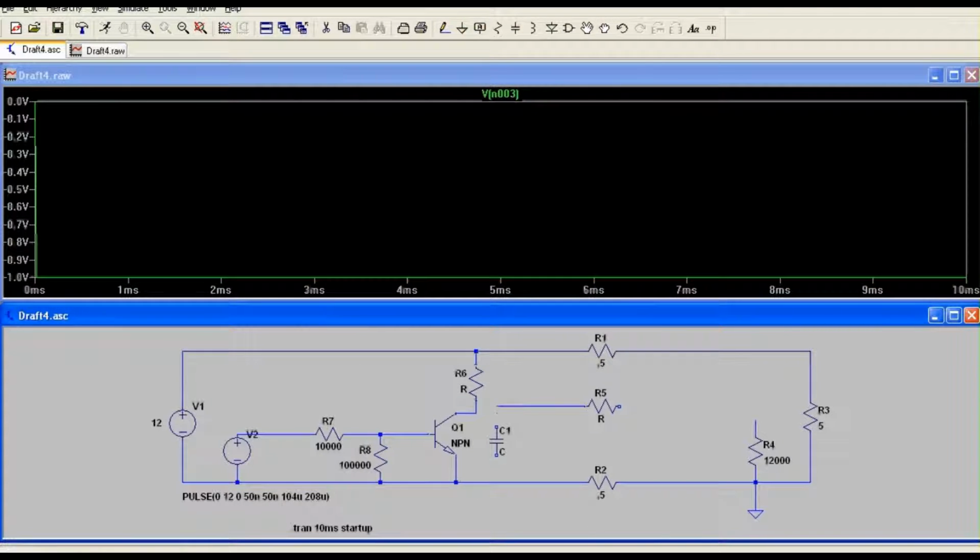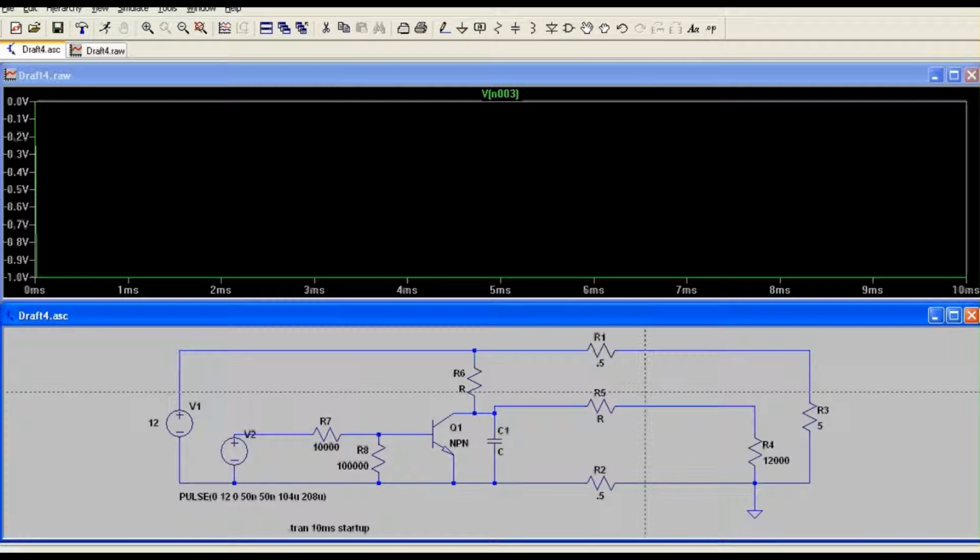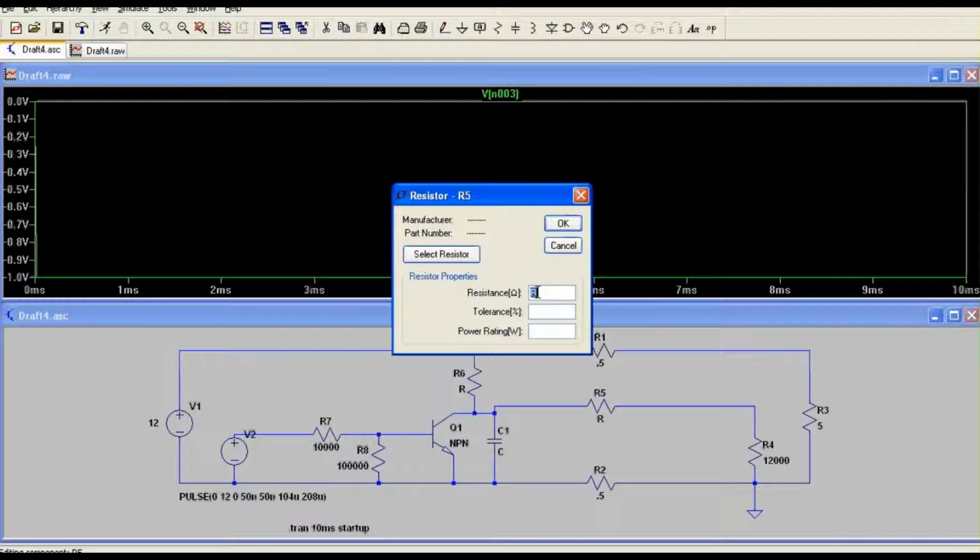So the next question is, you've got this problem. It is possible, depending on what that silicon receiver is, if it's not tolerant of those negative voltages, you can have some funny stuff happening. Maybe you'll kill the input to your chip. Probably not. What's more likely to happen is that whatever it's doing with it, or how it's going to produce an output, could be unpredictable.